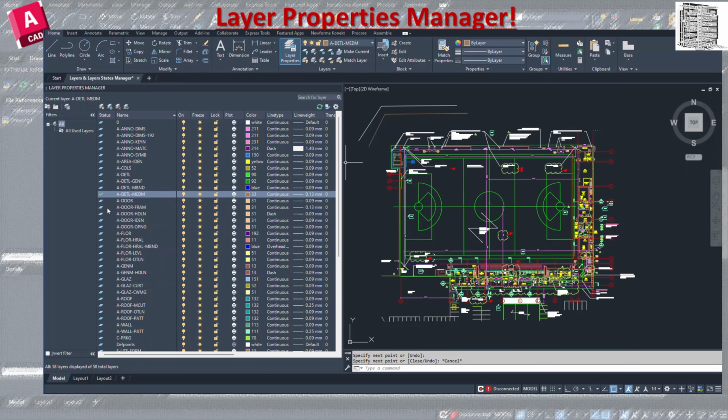So this is one thing that you can get, and the next thing is sometimes you can see these blue panel or white or gray. So blue means you have a layer and items assigned to it. If it's gray or white, it means that you have a layer but no objects assigned to it. So you might have a layer with the name and everything on it, but it hasn't been assigned to any object. So that's going to help you real quick to identify which layer doesn't have any associated objects assigned to it. You can identify it easily here.